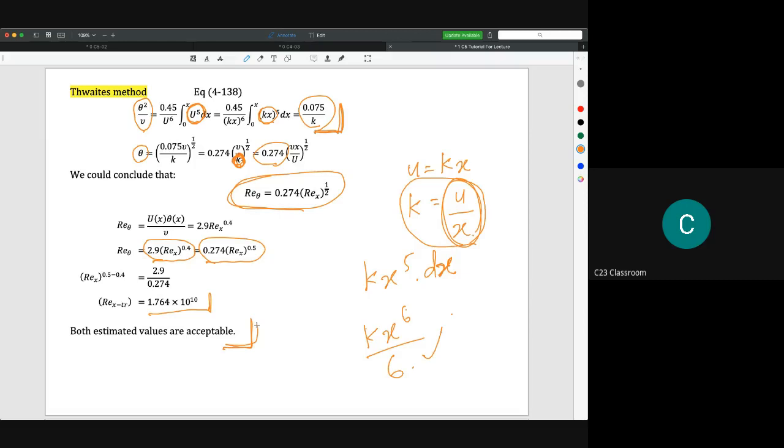Sometimes it may flow in a very thin, very small boundary layer thickness, but sometimes the wake occurs and so on and so forth. So they will give us a very high boundary layer thickness, for example. So the uncertainty for the turbulent boundary layer is quite high. That's why sometimes we could get totally different numbers from a few equations.